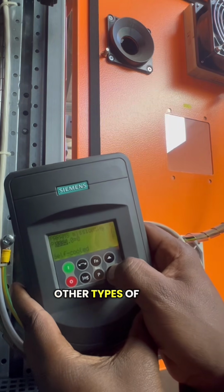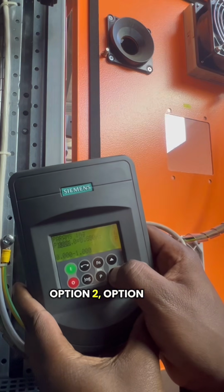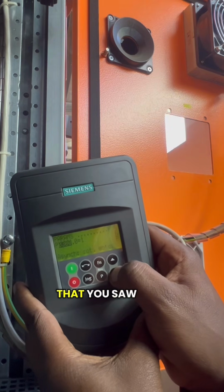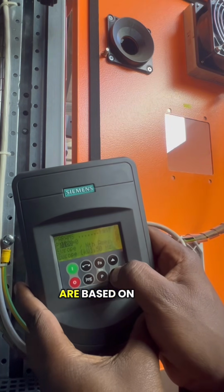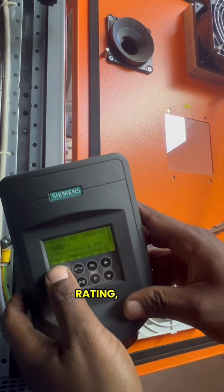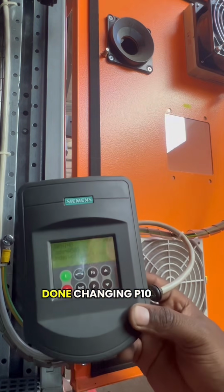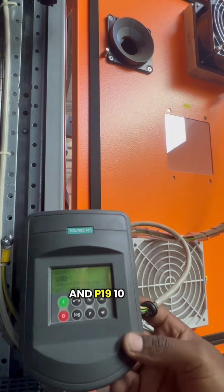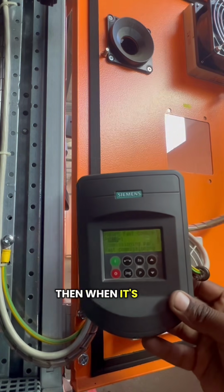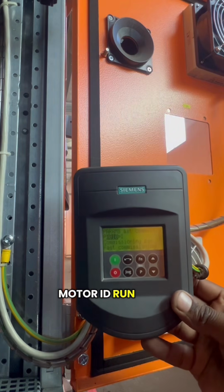But there are other types of ID runs that you can do. You're going to see when you get to option 1, option 2, option 3, and so on. All other parameters that you saw as I was scrolling down are based on the motor rating, like the current rating, the speed rating, the voltage, and so on. So once you are done changing P10 and P1910, you start your motor, you let it ID run. Then when it's done, it's going to put a message there on the screen: motor ID run successful.